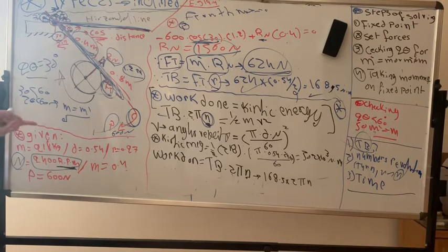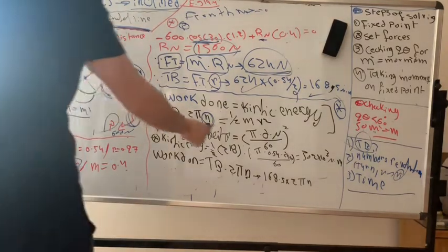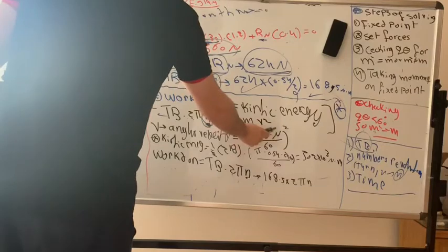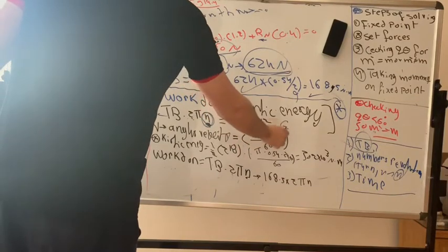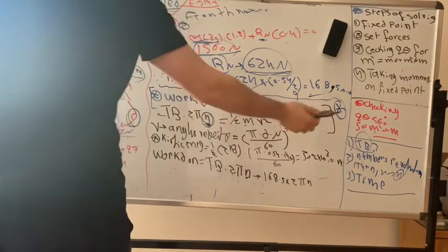So I'm supposed to have the angular velocity, not the velocity in meter over second. The angular velocity, because he gave me the capital N rotation in RPM. Great. So the angular velocity equals 2 pi n over 60, and easy peasy.